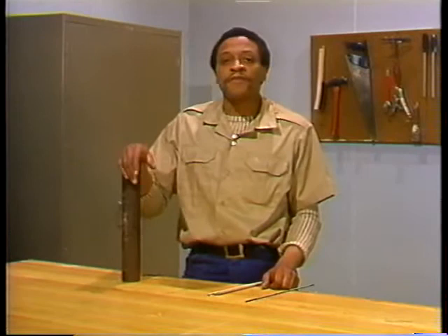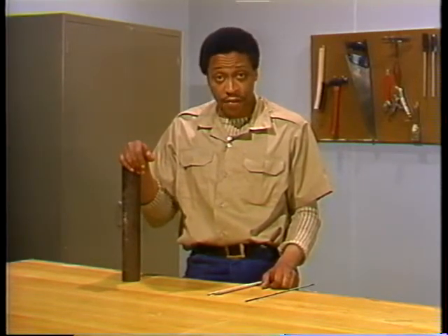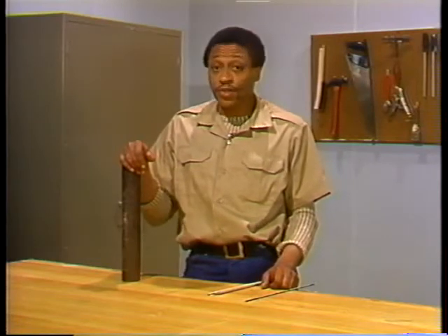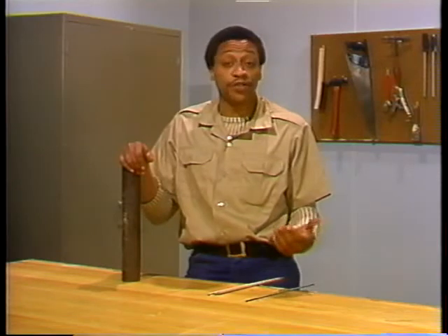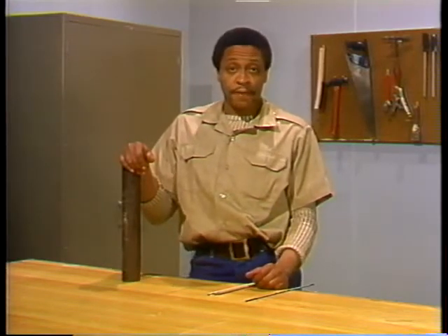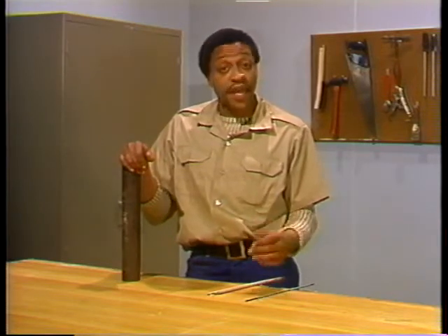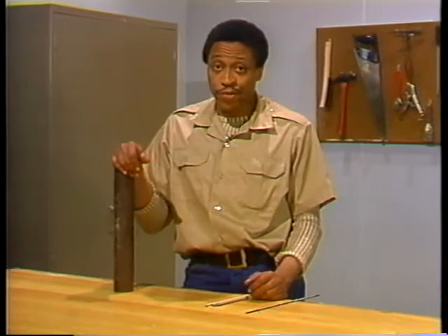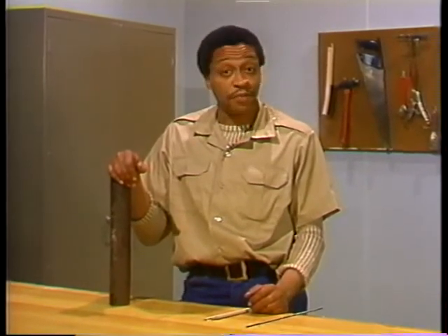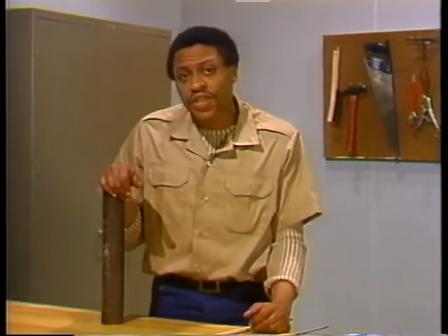Replacement of an entire tube section can be done to repair any kind of tube failure. Replaced tubes are as good as new ones. You can replace every tube in the boiler or as much of one tube as necessary. The problems with replacement of a tube section are that it is time-consuming and expensive. Still, it is sometimes the only procedure that can be used because the damage is too severe to be repaired by any other method. When getting ready to assist in a repair, be sure you're thoroughly familiar with the procedure.